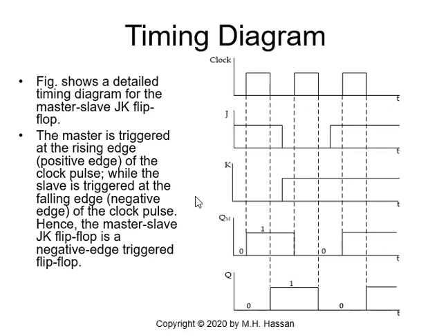Now the timing diagram of this circuit, if we assume J and K certain values, and we look at the clock pulse, and we look at the positive edge, at the positive edge, the QM will change from 0 to 1. At the negative edge, if J is 1 and K is 0, Q will change from 0 to 1. So QM will change on the positive edge, while Q will change at the negative edge based on the values of J and K. And depending on J and K from the table, we can determine what Q plus is going to be.